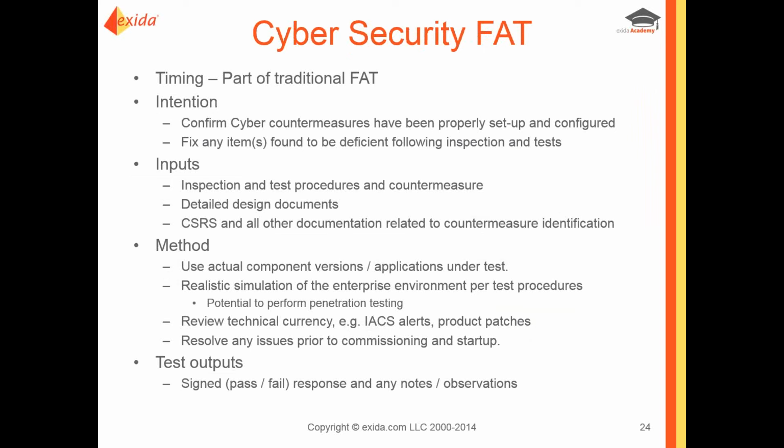Timing of the cybersecurity FAT. The thing that makes the most sense is to actually make it part of the traditional factory acceptance test. Once again, the intention is to make sure that those countermeasures that can be inspected and tested have been properly set up and configured. Just as with any other FAT, any items found to be deficient need to be fixed.